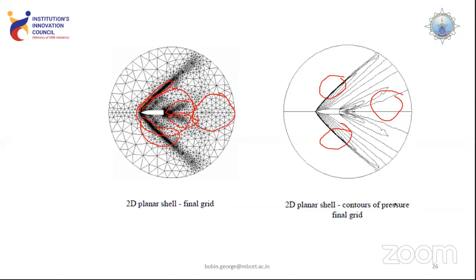The advantage is that you can reduce the amount of computational time when you are employing fluid dynamics behavior. Suppose I create a fine grid size like this throughout my mesh, including this area also. Whatever system I am employing will be unnecessarily computing values over here where not much effect is generated. So I am investing much computational time in areas where the computation need be low. Also, if I am placing these coarse grids over here, this shock phenomenon being generated, this sudden change in pressure, won't be captured. That means my result won't be that accurate. So these are the two faces of the coin that you are facing.